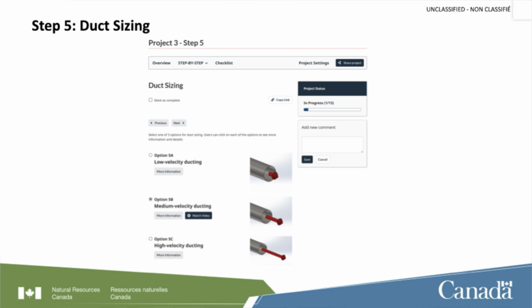So one of the solutions is actually changing how our delivery system works. It's not necessarily increasing the size of the furnace, which used to be the way we thought. Let's look at the delivery system and how that works. So low velocity ducting, it operates at around 0.5 inches of static. And it's served us well for as long as we've had indoor heating systems.